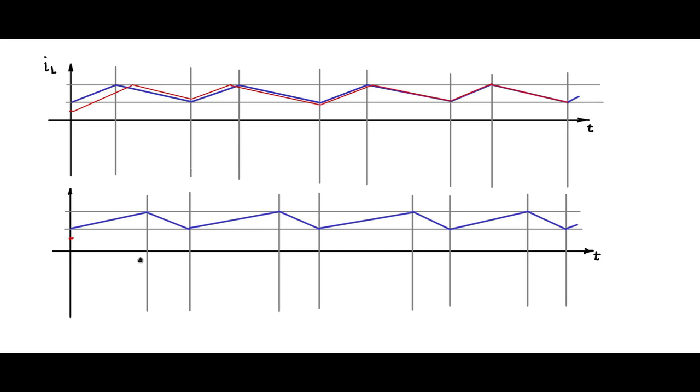So when you introduce a disturbance, from this point onwards it will start going parallel to this line. It will have the same inductor slope. So let us say it takes this line, hits the top value here, that is the IL reference value, then goes down, resets again, because this is the time duration when the Q of the flip-flop is low.